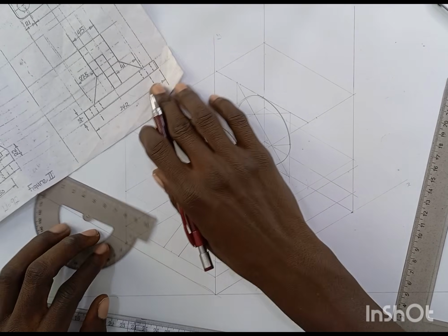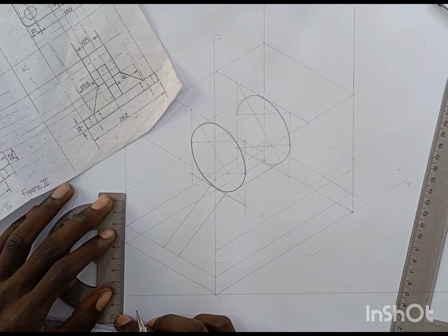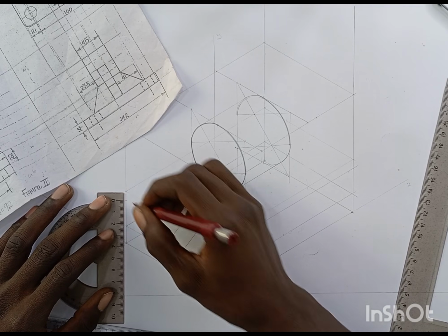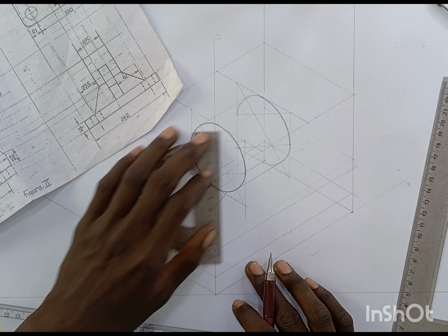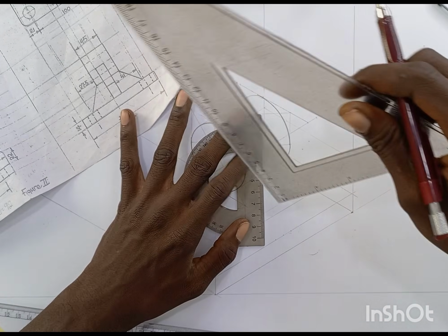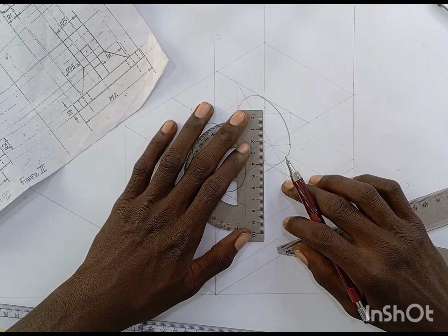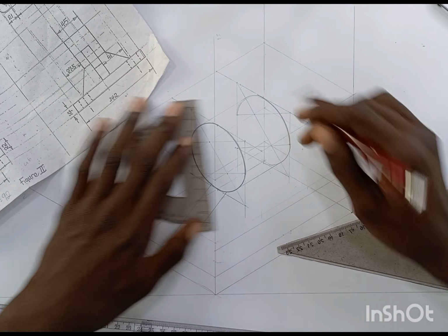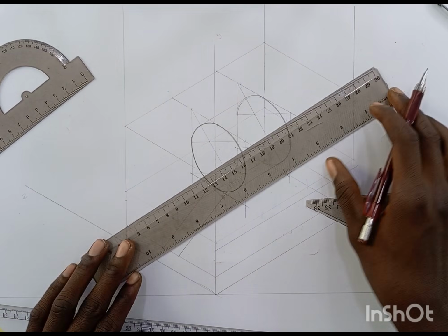Okay. So the same thing, whatever you did here, we are going to do the same thing at the back. So here also I'm going to measure 22. This is my point 22. So I'm going to do the same thing here also from the other side. But if you're having a very good set square, you can just use it like this to strike. So I will measure 22 here. This is my point 22. So I will now connect these two points also together.